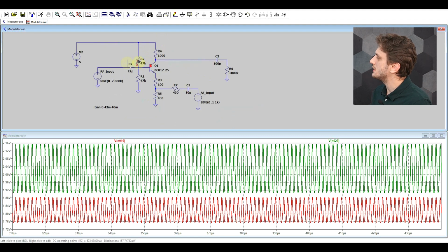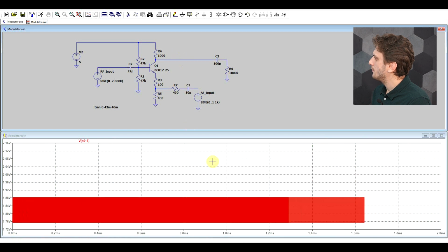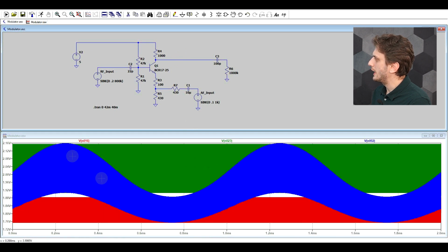And this is what we see with our first circuit, where we have both the audio frequency and the radio frequency signal. We see our amplitude modulation, so we see our radio frequency signal being modulated by the audio frequency signal between the two extremes. So between when we had a roughly 80 millivolt input signal multiplied by 3, and when we had a 40 millivolt signal, again amplified by 3. So the circuit works. Not much left to do, but try to build it.